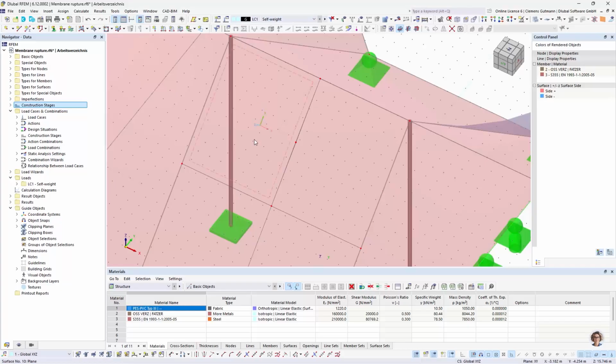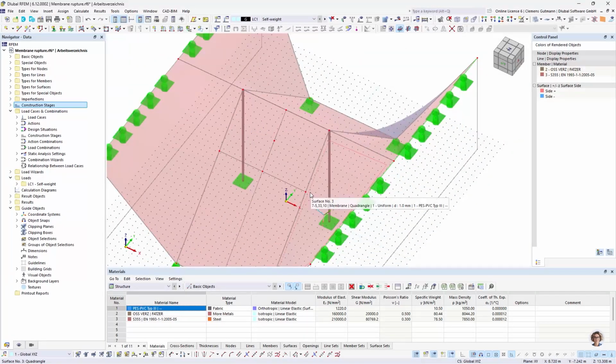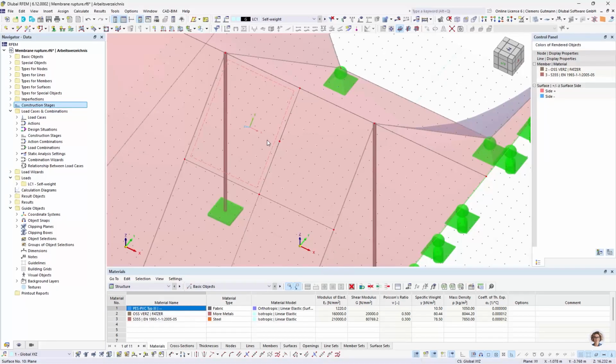And what we don't see is how the panels are actually placed on this membrane. For this project, I imagine that there is a weld at this line and also at this line, and the weld has roughly double the thickness of the membrane, and therefore is a lot stiffer, and it's not very likely that the weld itself will rip.